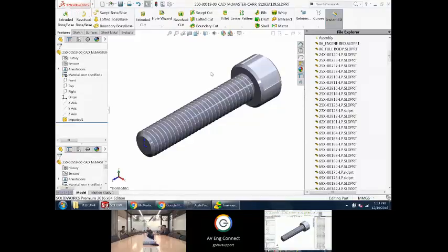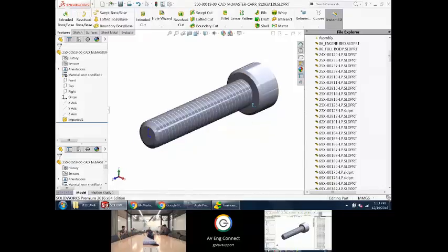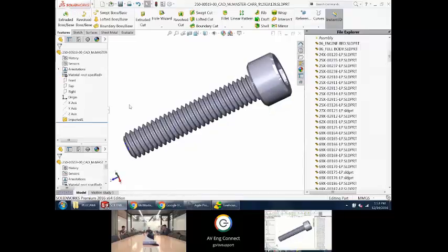But if you turn it to hidden lines visible, or you make the part that's around it transparent and you can see those threads, now when you're rotating this thing, if there's 144 parts and they've all got threads, it's got to do 144 threads every time you rotate. It's got to redraw those. And so you'll see hangups in your graphics if you've got a lot of over detail like this has.